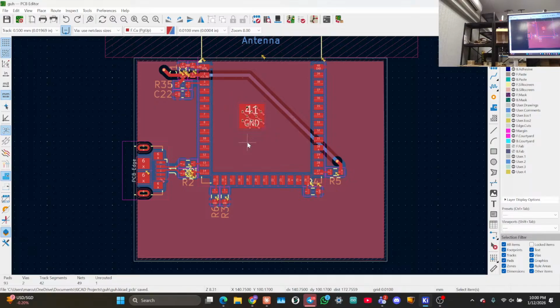Actually, there's nothing wrong with using wire cores for power as well. There's really nothing wrong with it. It's just that usually you don't need it. You want the power to be everywhere across the board, so you just stick to it. Because when you have a whole plane which is ground, you just via down into it. When you have multiple layers, it's very useful, instead of routing things, you just via all the way down to the ground.